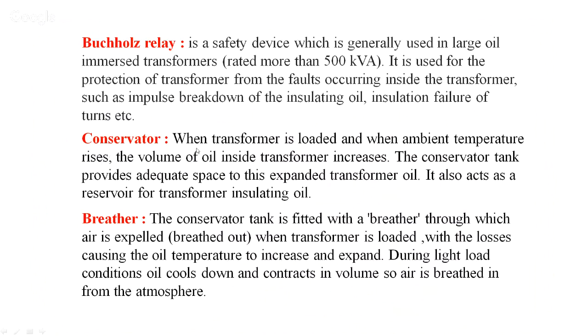Conservator: when transformer is loaded and when ambient temperature rises, ambient means the surrounding temperature is going to increase, the volume of the oil inside the transformer increases. The conservator tank provides adequate space to this expanded transformer oil. It also acts as a reservoir for the transformer insulating oil.